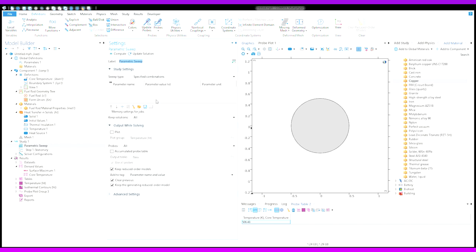All right, so we're going to do a surface temperature sweep. We're going to change the surface temperature to see what is the highest surface temperature that could exist that would still be below that 650 Kelvin safety limit. The parameter we're altering is the surface temperature, so Tsurf. And then I'll briefly talk about the sweep type.